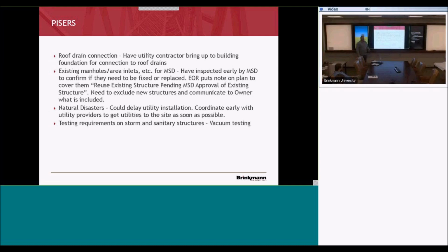Sometimes if you're getting the site early and maybe it's broken up and there is a different site developer, a lot of times a phone call, you talk to them, hey, if I give you the location, will you run it to here, versus just stopping 5 feet out from the building. But in order to do that, you've got to have your surveyor on board and you've got to have clear locations of your downspouts, your roof drains, so you don't have the issue where it comes down and then kicks over. But if you can do that, that'll save you some money.